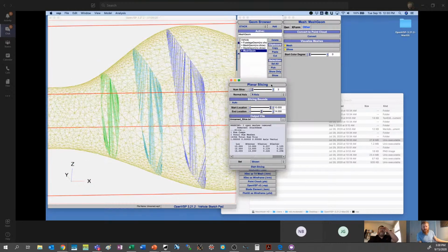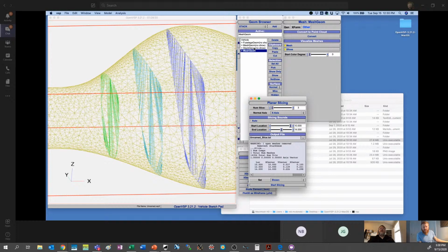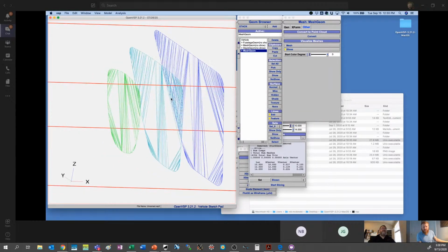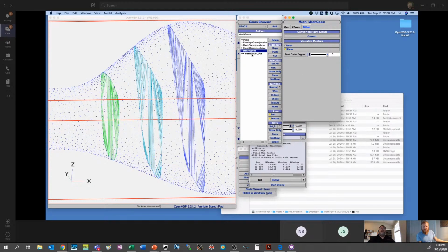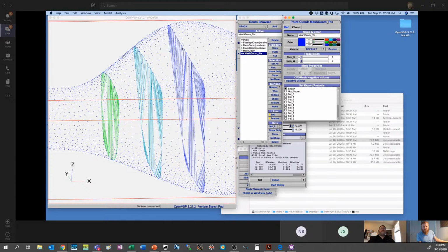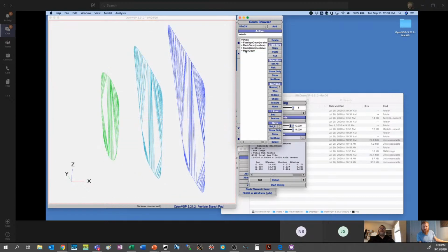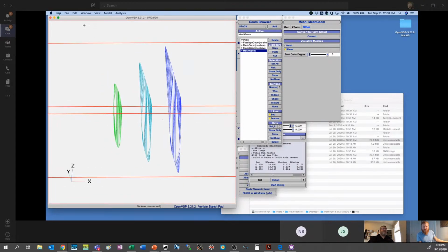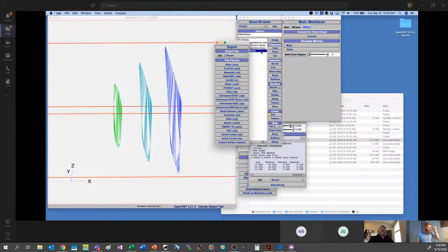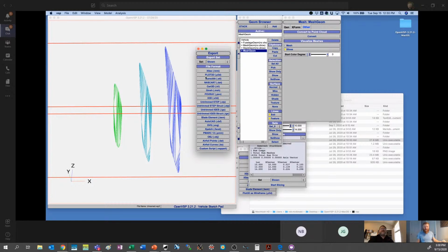And the great thing here is that created it as a mesh geom. So first, we'll come in here, but we only want to look at it as the slices. And if we do that and we convert it to a point cloud, what we have, okay, that it did both. Let me delete that. So we're going to need to export this. I know this is more steps than it ought to be. So what I do next is I would export this, which is just exporting the shown set. So it's just exporting these slices as an STL.